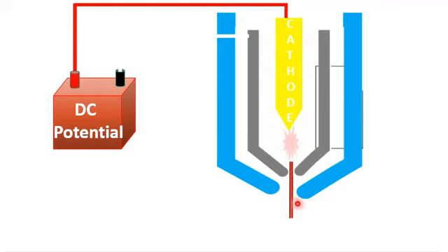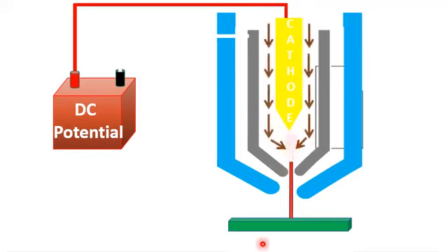Dear student, please note that the cathodic arc deposition system, as I have previously discussed, has an electrode, which is a cathode that acts as a precursor material. Usually the material from the cathode is extracted, transported onto the surface of the substrate, and then deposited onto the surface of the substrate in cathodic arc deposition systems. The cathode usually used is metallic in cathodic arc deposition systems.